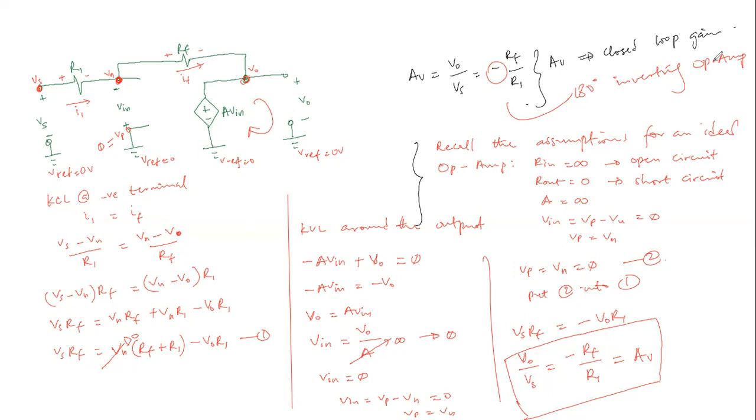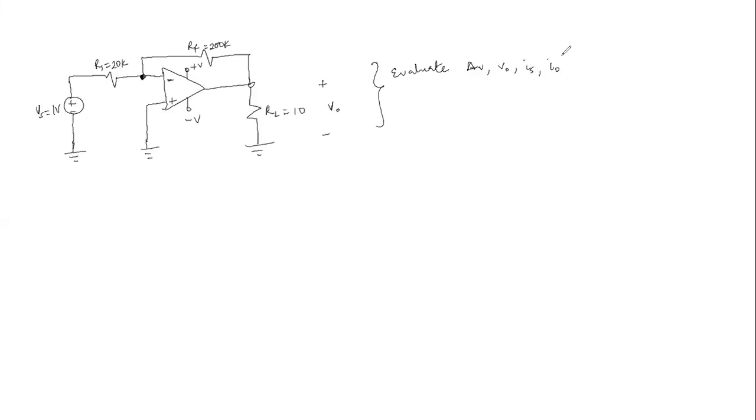So technically, regardless of the infinite open loop gain that we have here, a closed loop gain of some finite value of probably some designated value could be designed by choosing an appropriate value of the feedback resistance and the input resistance, or better still R1, not the input resistance, the source resistance. Okay, so let's consider a simple example. So here's a simple inverting op amp.